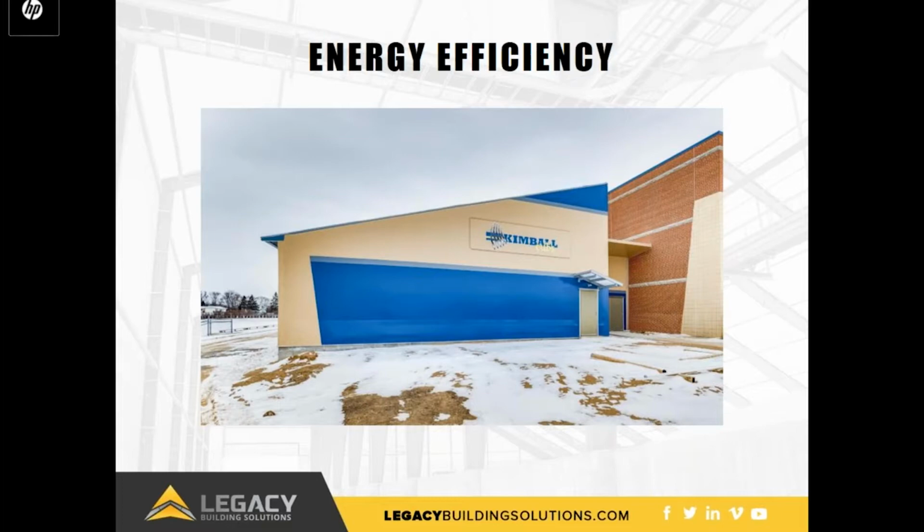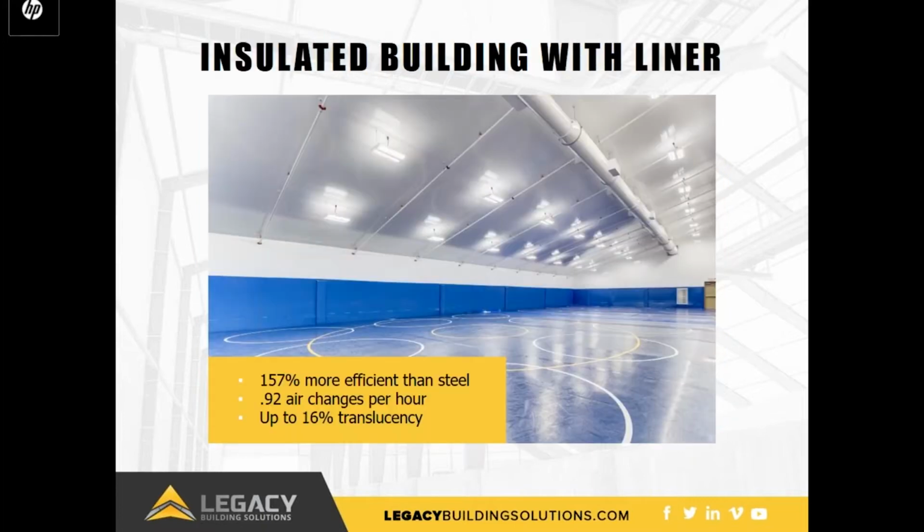Finally, overlapping metal panels do very little to prevent air leaks or provide a weather-tight finish. The tight seals and lack of holes in the building envelope create a building that is less drafty than a comparable steel building. In fact, independent testing has shown that Legacy buildings are 157% more efficient than a comparable steel building. An air infiltration test at this multi-sport building in Minnesota showed an impressively low 0.92 air changes per hour.